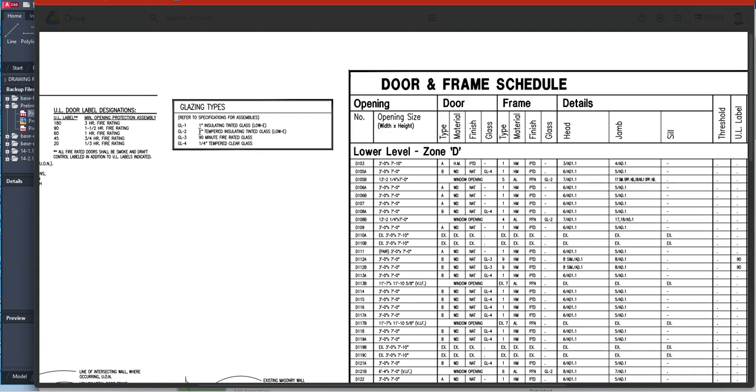It doesn't mean that the glass itself is 1 inch. It could be a low E, which means two panes of glass with argon between them. It's insulating, and it's also tinted at the same time. Insulating means they pump some gas in between two glass sheets and seal the sides, so that helps the insulation. But that's basically it.